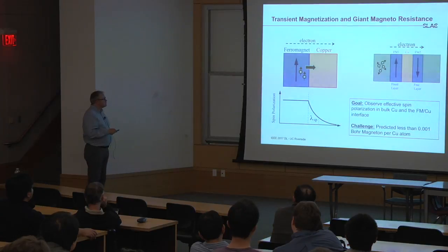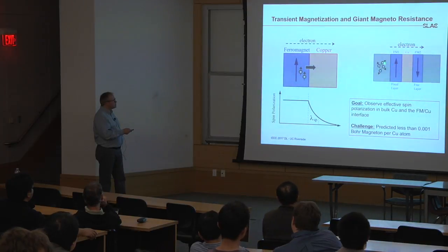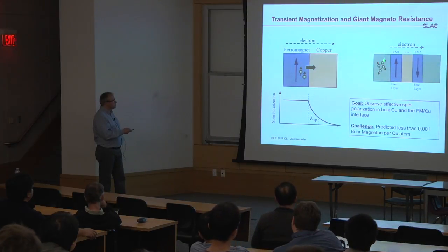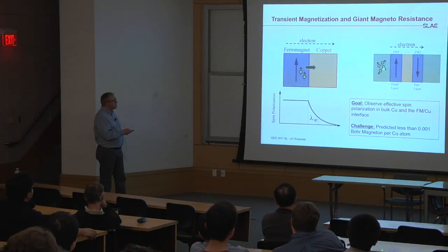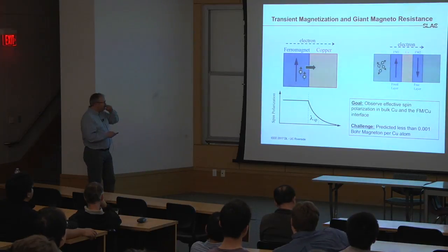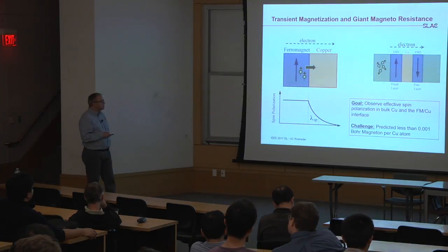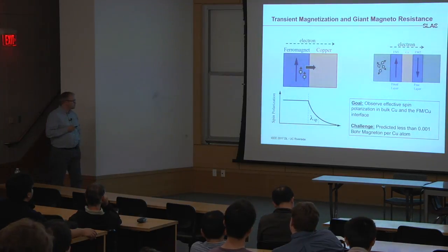What I mean by this is, if you run a current from one material through the ferromagnet, you have, for example, spin up and spin down electrons in your current that's going in. Only spin up, or mostly spin up spins will make it through the one ferromagnet into the copper. The others will be rejected. And then some of these spins will make it through the copper, and it depends on how many spins really make it to the other layer what the exact resistance is.